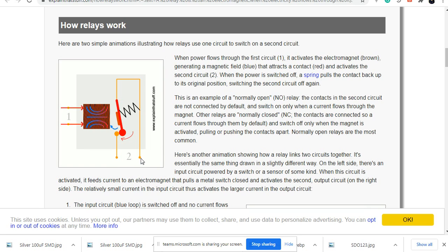One is the live wire, the other one is the ground wire. Now supposing on this side, where my cursor is at present, I have the live wire connected over here. So when the device is turned off and then I turn on my DC over here, and certainly this is going to be done by a transistor, this relay is going to be turned on. The fulcrum will move towards this position, and the device is going to be connected at this point where my mouse is, and the device is going to be fed the live wire.